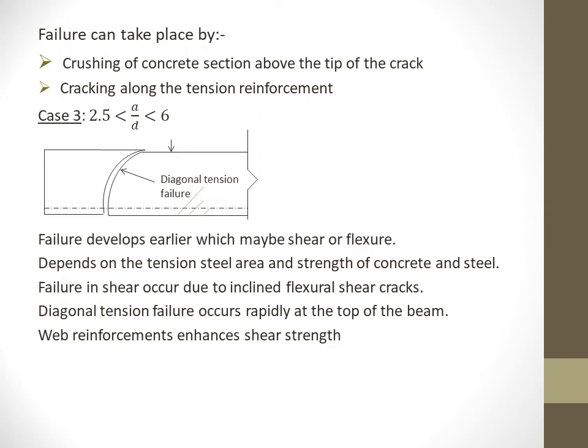It increases significantly in the case of the a by d ratio being less than 2.5, hence it requires heavy loads to cause inclined cracking.